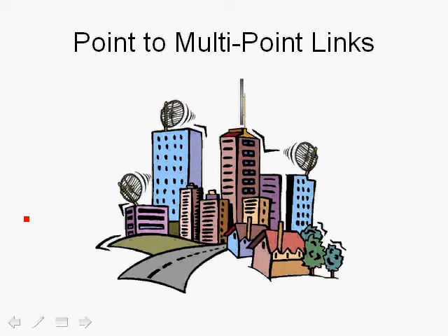In addition, it may be that we can achieve line-of-sight communications between terminals, or we have non-line-of-sight situations. For example, in communications with mobile subscribers. In both cases, we have to consider the terrain, foliage, atmospheric conditions, and interference. In an urban environment, many times we don't have line of sight, and communication is possible through multipath and scattering through the multiple buildings, and the received signal exhibits multipath fading, and there are challenges in designing reliable communication systems in those environments.